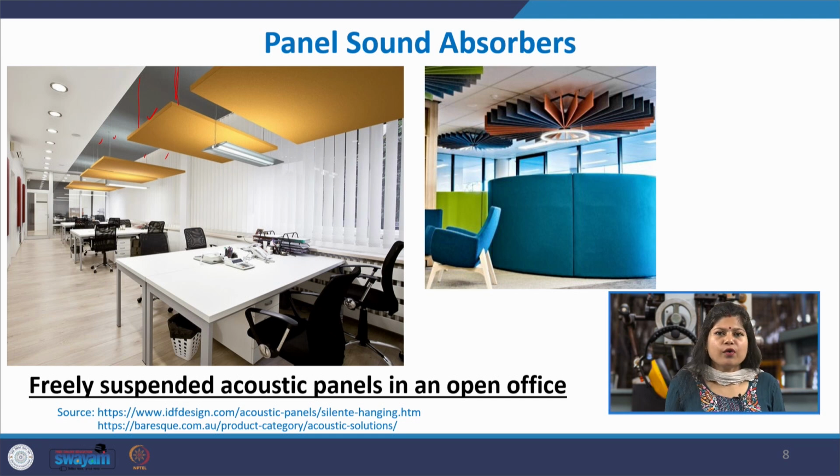Although they really add to the aesthetic quality, because they are nice, glossy and shinily painted, they are actually added for the acoustics purpose. They are added to enhance the acoustics inside this indoor office space. They act like a panel absorber and they try to absorb the irritating low frequency noise.